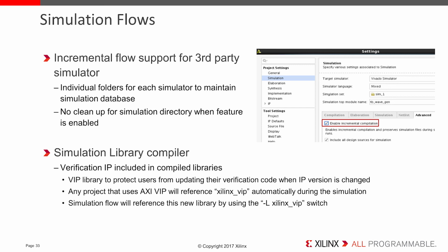Verification IP is now included in the simulation library. This is a versionless VIP library that will protect users from updating their verification code when the IP version is changed. Note that any project that uses AXI VIP will reference Xilinx VIP automatically during the simulation.